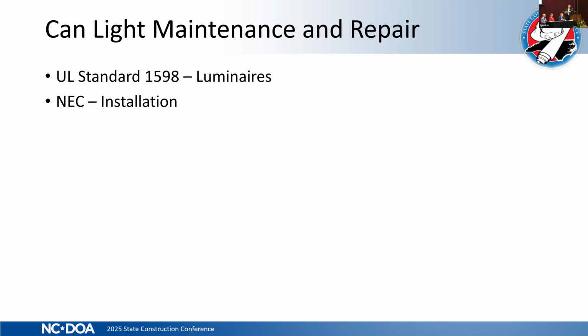Or you got to have a catwalk above it, a door next to each one of them. One of the things I've seen, NC State's got some over in the classrooms, they'll have a section of tile ceiling with hard ceiling adjacent. And it creates an interesting pattern across the room, but you're servicing the stuff that's in the hard ceiling from the accessible tile that's right adjacent. And so there'll be these funky little patterns all over the ceiling. Partly, I think, now that I'm looking back at it, they knew you needed access to get to those LED type fixtures.